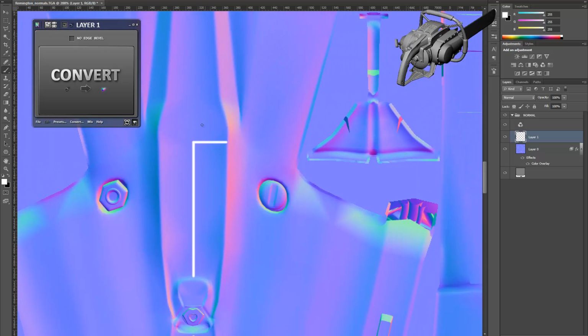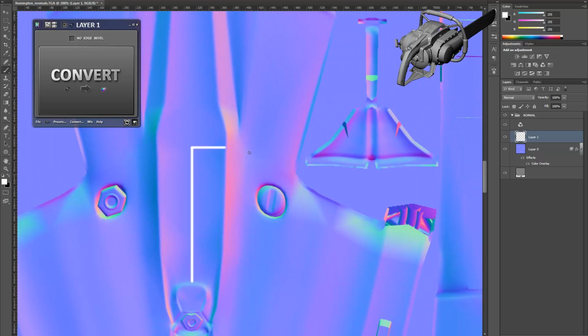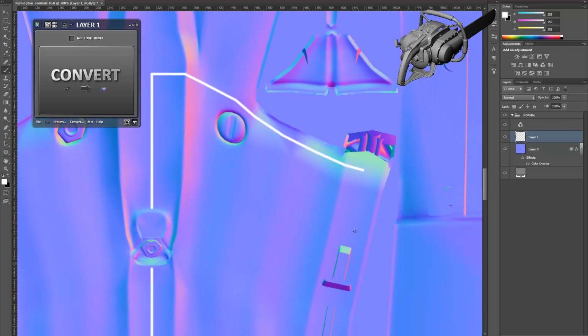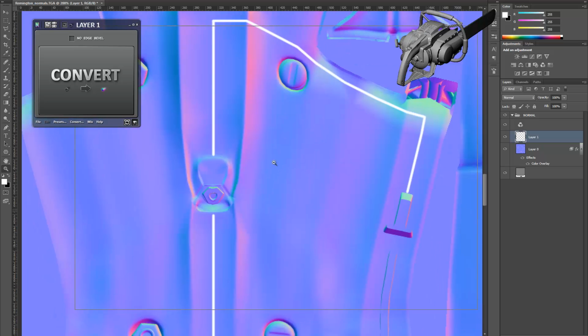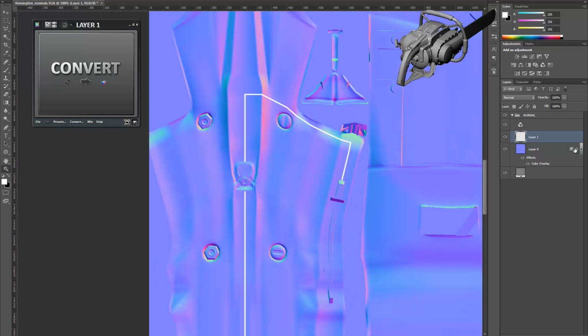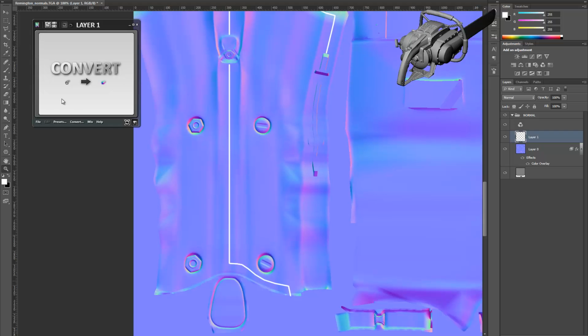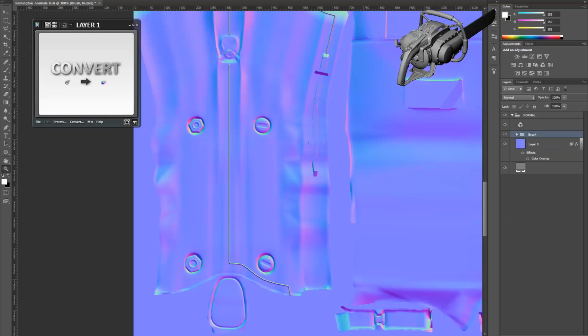And this is the tricky part because here's a UV distortion. But I'm gonna try and see if I can get it on the first try. Down here. Keep going down. And down here to the bottom part of the grip. And just straight down to the trigger. There we go. Alright, so now that we're done, I'm gonna click Convert Brush to Normal, which is the icon you see here. Click it, and there we go.